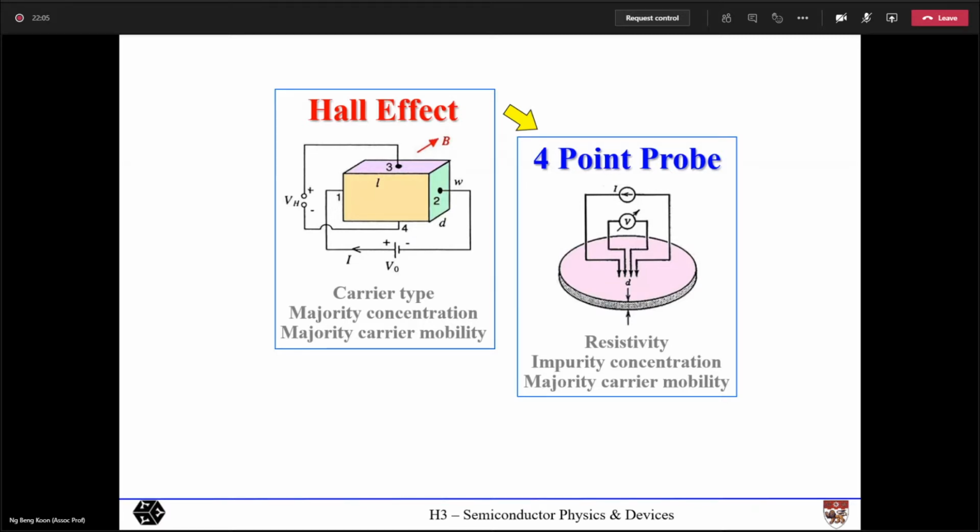At the same time, because we're measuring in an inner portion of the current that's driving through the semiconductor, the part where the probe delivers current into the semiconductor, where the spreading is occurring, is also avoided, because you're measuring the middle part where the current has become parallel to the surface of your wafer. So although this type of measurement is quite simple, it avoids the effect of this unwanted resistance of contact and spreading.